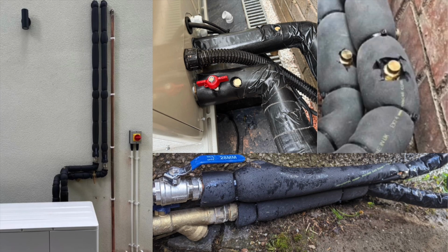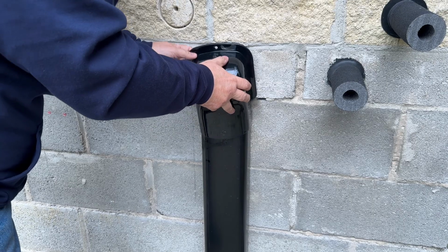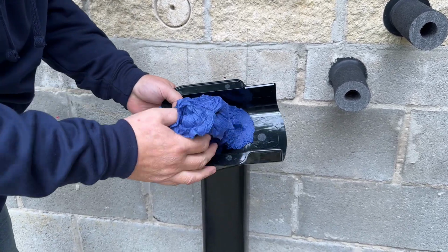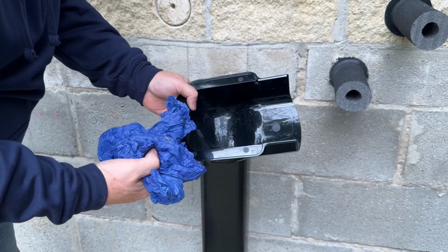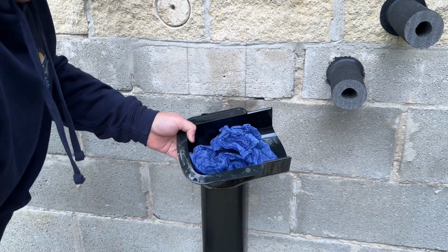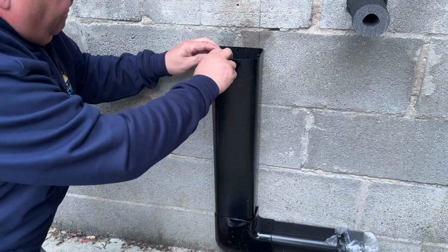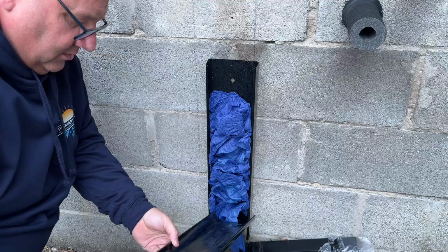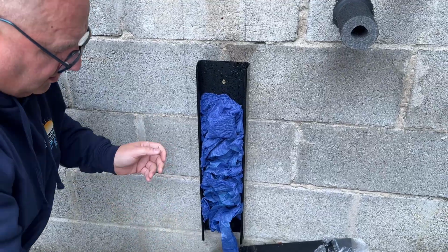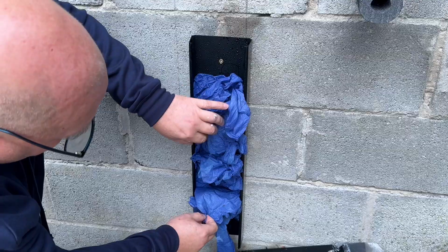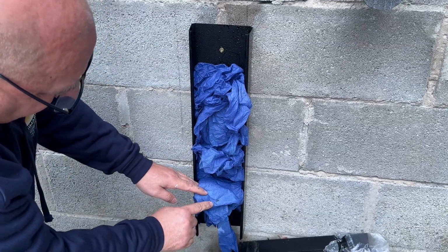And then we look at, a lot of people use plastic trunking. Now, plastic trunking is just a shroud, a cosmetic shroud. It still lets all the water in. So the insulation inside there has to have all these properties as it would if it was outside. So it has to be sealed up correctly, clipped correctly. The water diffusion has to be high so it doesn't absorb the water, because it will have its own climate system inside that plastic trunking. And it can never get dry because it's inside the plastic trunking.